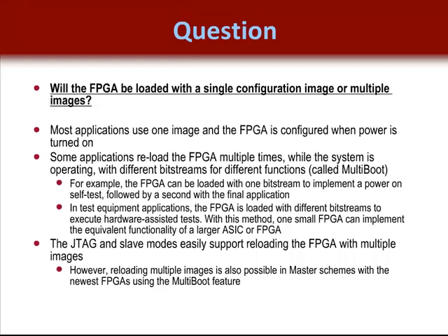Another question is, will the FPGA be loaded from a single configuration image or with multiple images? Well, if your application needs multiple images, there are some nice FPGA features to consider. The solution to this problem exists in Xilinx's newest FPGA families and is called multi-boot. This allows an FPGA to configure with different bitstreams on whatever occasion the designer would like. One of the best examples of this is during a hardware-assisted test. In this scenario, the FPGA is loaded with a bitstream to perform the self-test, followed by another bitstream with the final application. The JTAG and slave configuration schemes are frequently used during debugging for this purpose just as well.